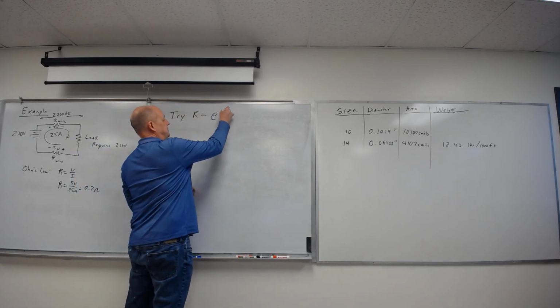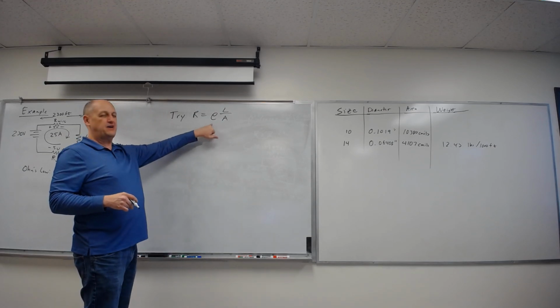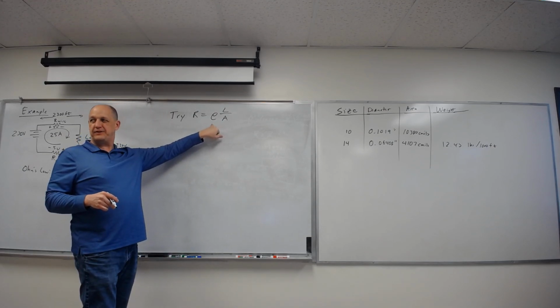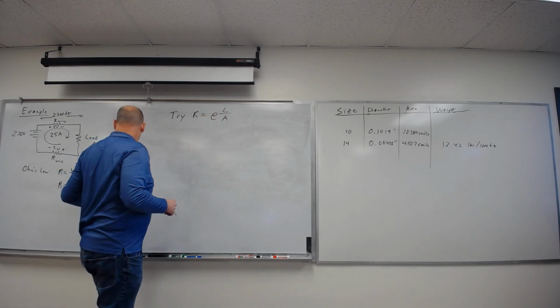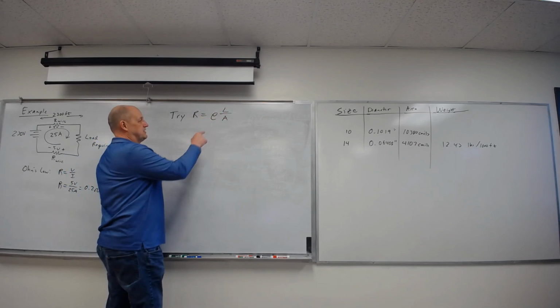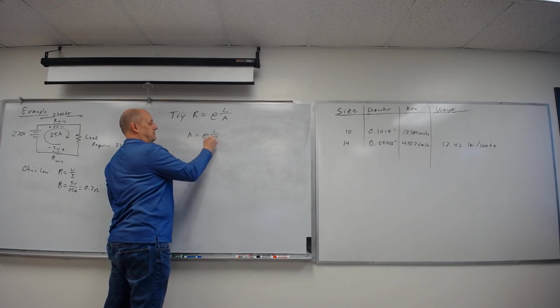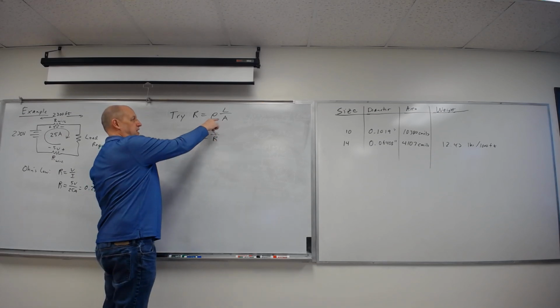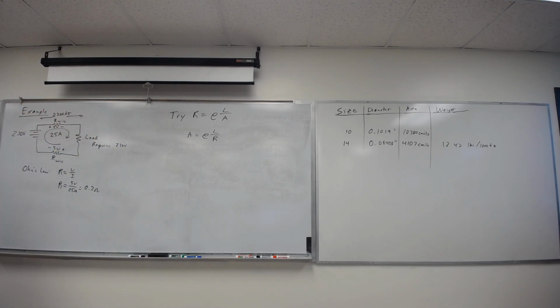Resistance equals rho L over area. Okay, it's definitely copper. We'll talk about different materials and resistivity in a second. The length is set. We said, oh, it's got to be 0.2 ohms. So I can solve for area, right? So area is going to equal rho L over R. Right? I multiplied both sides by area over resistance to isolate area. Yeah. I know. That nasty algebra.